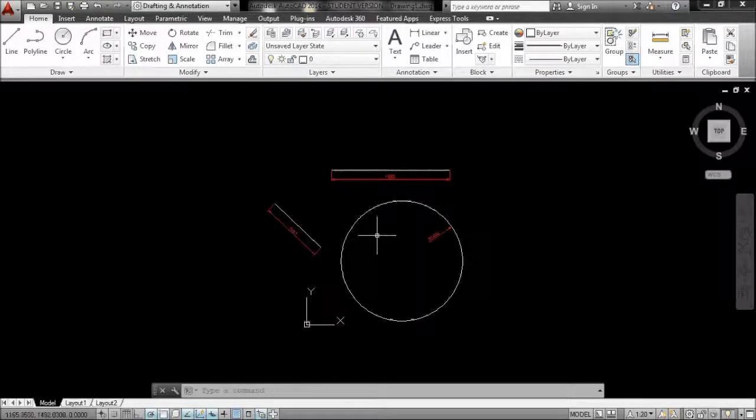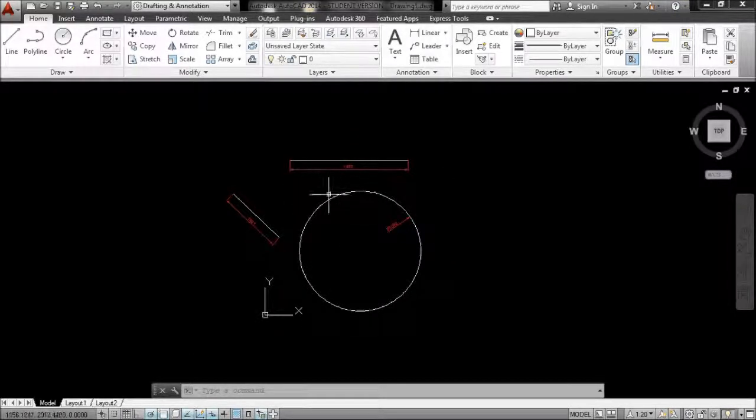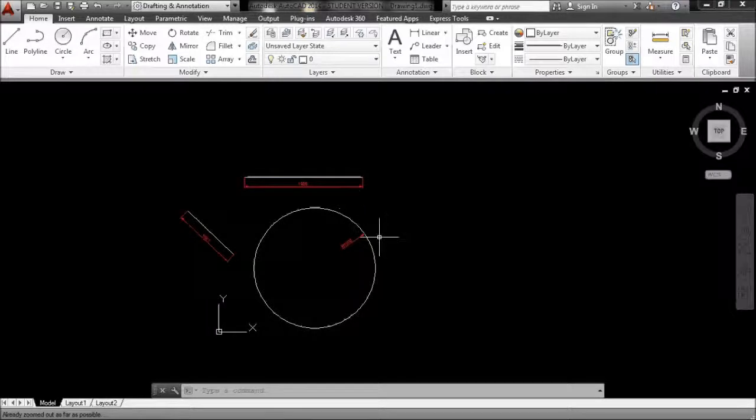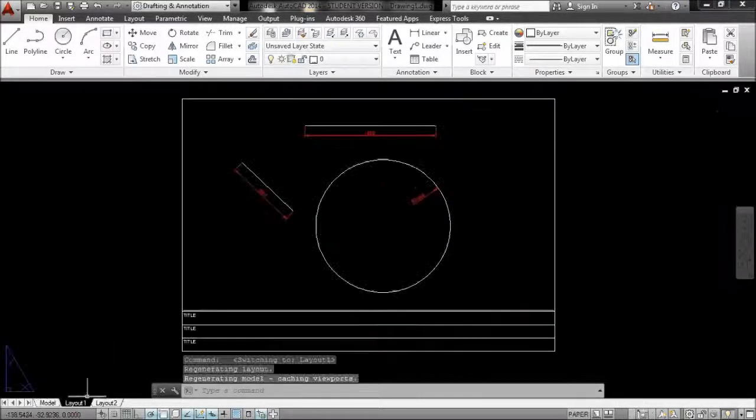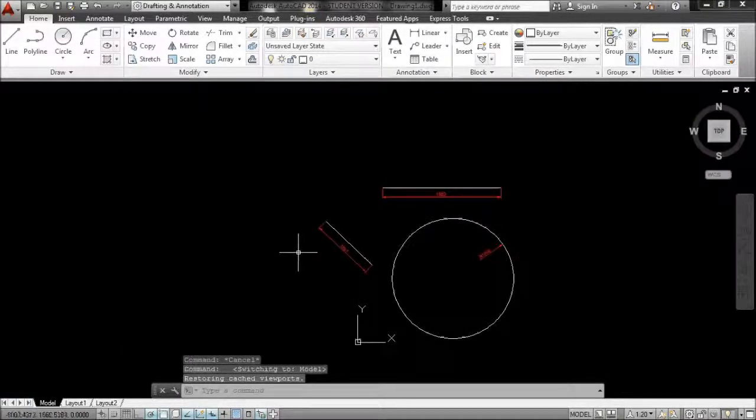So do all your dimensioning and your modelling and all this stuff in here, 1-to-1 size. CAD is an infinite size sheet of paper, so you can never outdo it. And do all your presentation stuff, your title box, logos and everything in here. Set it to scale, ideally before you put dimensions on. And that really is it.